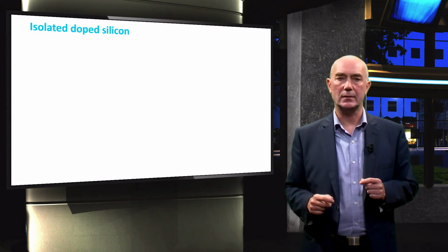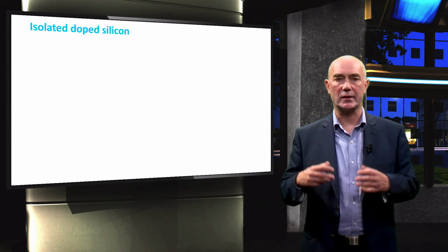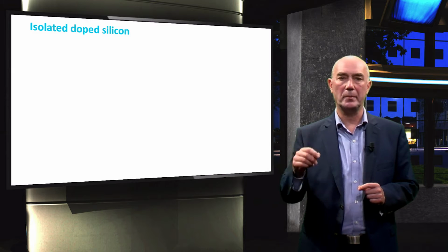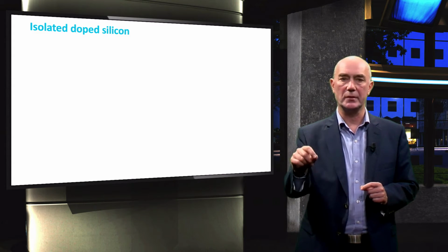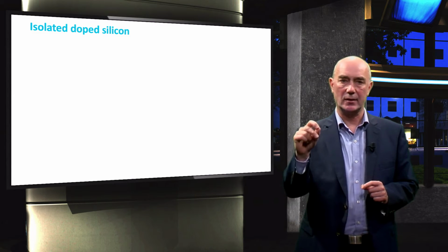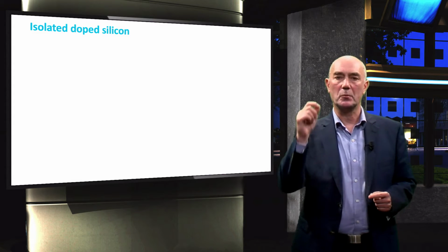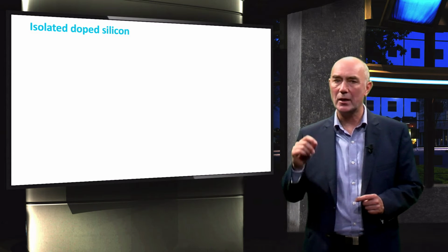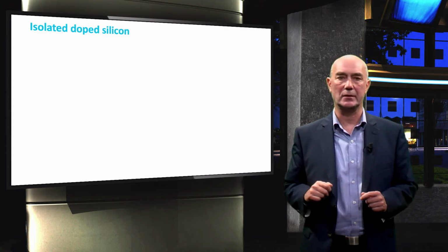Before we get started, I should note that the bonding diagrams here are severely exaggerated. We will show more dopant atoms in the diagram than the normal concentration of dopants in the material, in order to get a sense of what is happening. In reality, only 1 out of every 10,000 or 1 out of every million silicon atoms is replaced by a dopant atom.